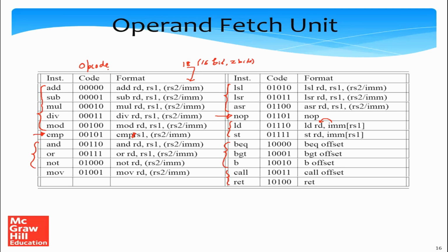So the question is, why have we given the opcodes to the instructions the way that we have? Let's take a look at the branch instructions first. Essentially we need to look at decode complexity. If we take a look at the branch instructions, we'll see that all the branch instructions have been given an MSB of 1. So in that sense, it's very easy to find if an instruction is a branch or not. We just need to take a look at the most significant bit of the opcode and see if it's 0 or 1. That's very easy.